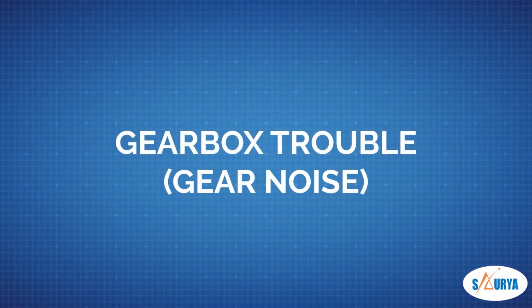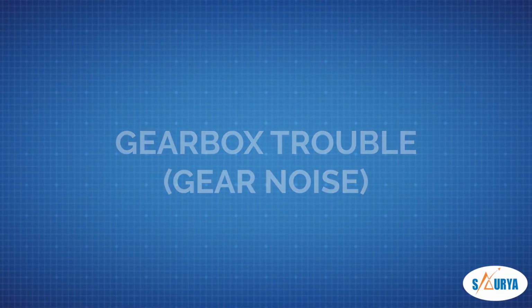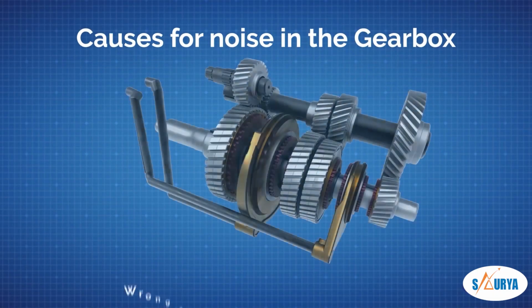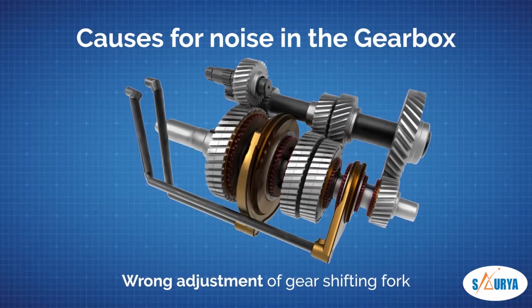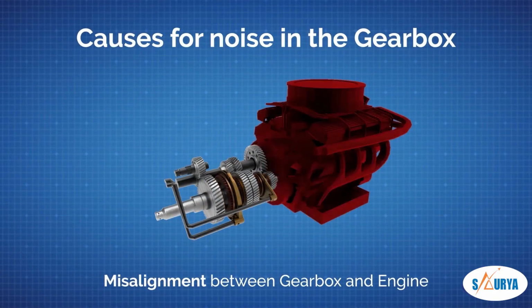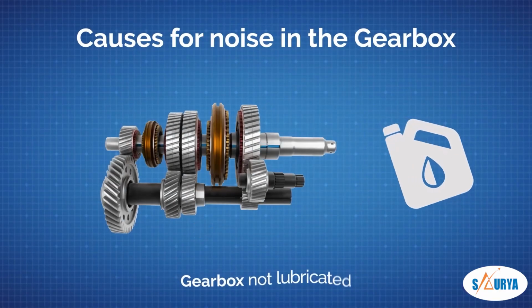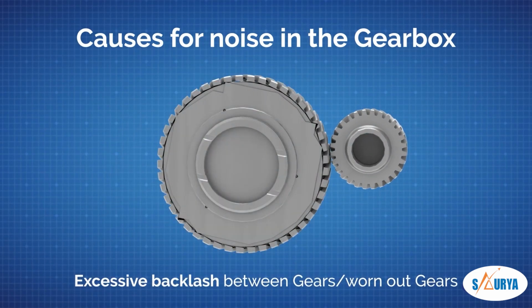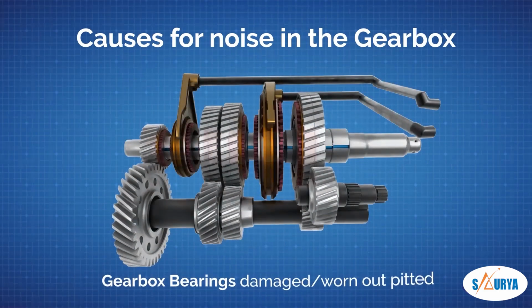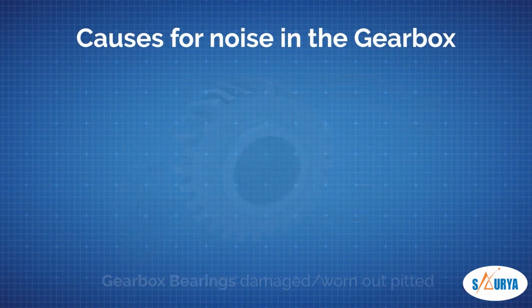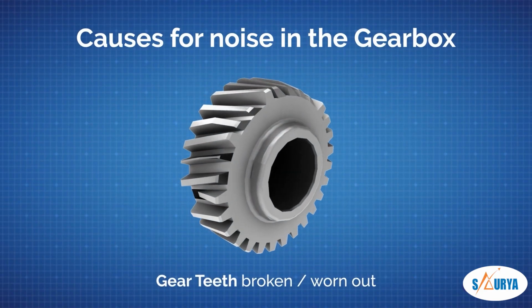Gearbox troubles: gear noise. The following are the causes for noise in the gearbox: wrong adjustment of gear shifting fork, misalignment between gearbox and engine, gearbox not lubricated, excessive backlash between gears, worn out gears, gearbox bearings damaged or worn out, pitted, gear teeth broken or worn out.